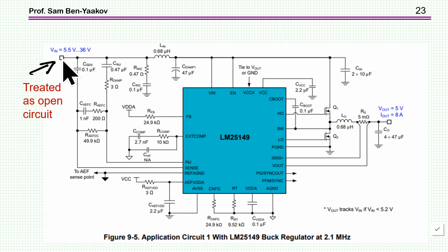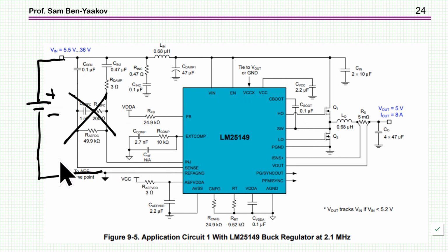Again, if this is an open circuit, then of course this stands by itself, but in reality, if, for example, you have a low impedance source connected to this bus, then this doesn't work, because the operation of this depends on a ripple here, and if you have a low impedance, all the current actually will go into the source, and this will not be operated. So treating it as an open circuit without talking about the impedance here is really not a way to go.